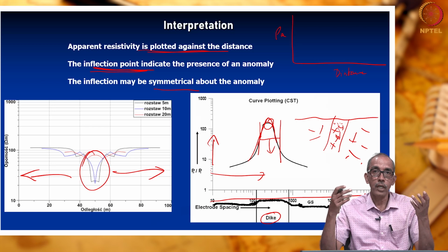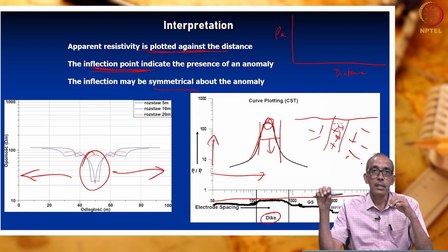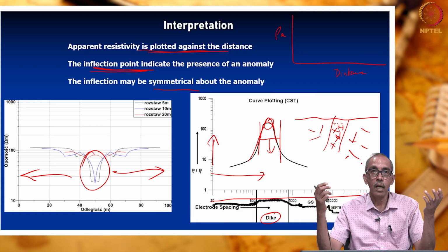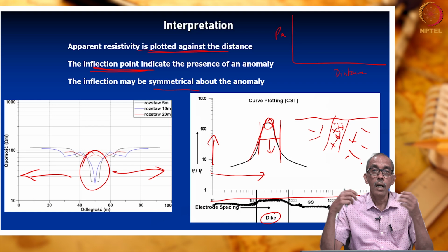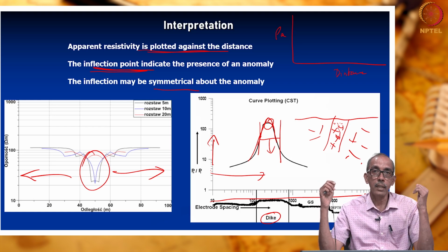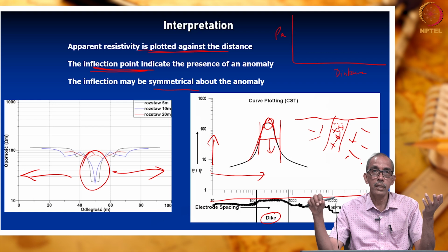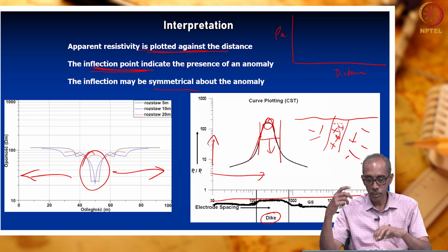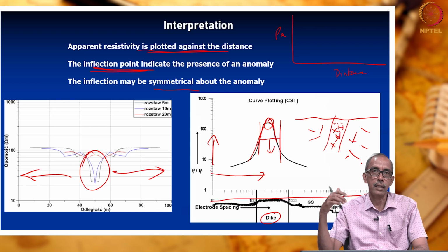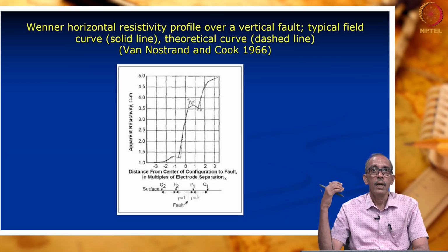Even for transporting oil, it is mandatory that we carry out a survey to understand the subsurface geology. Suppose pipelines or even electrical cables are going to several hundred kilometers. To understand a long profile before carrying out the actual work, we try to understand the subsurface by the electrical profiling method. Right. Here are some examples.